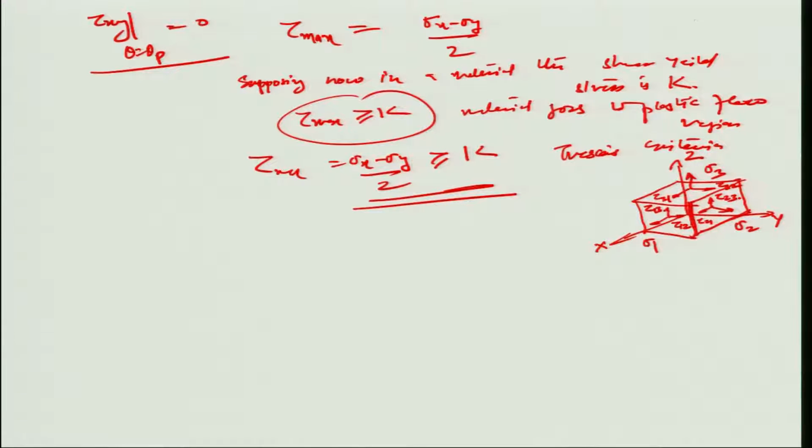let's say for example if you are considering only the rolling process, the states of stress which really matter are the xz plane, if we look at it in that manner, and y typically the dimension is so big that there is hardly any deformation or any strains which are of considerable nature in the third y direction.